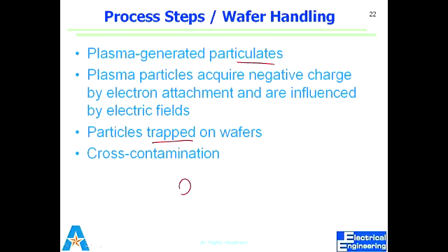Many times I would always do a de-scum before I do my process. And to be nice to the next user, I will do it at the end of the process. We don't do de-scum with a wafer inside. We do it on an empty chamber.